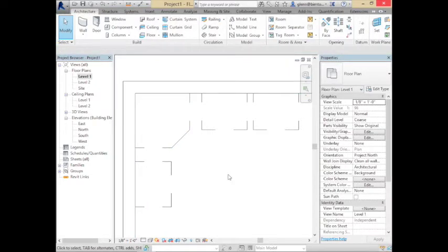And then to line up the other cabinets, I tend to use the align tool and lock cabinets together. The reason I like to do that is if the cabinets move, they all move together as a big chain. I think even some of you for the assignment found complete kitchens as a single piece online, like on Revit City. And how they made those was they just took a bunch of pieces and stuck them together and locked them. And yeah, you can make components which contain other components which contain other components and get really, really meta. Just making whatever's useful to you.